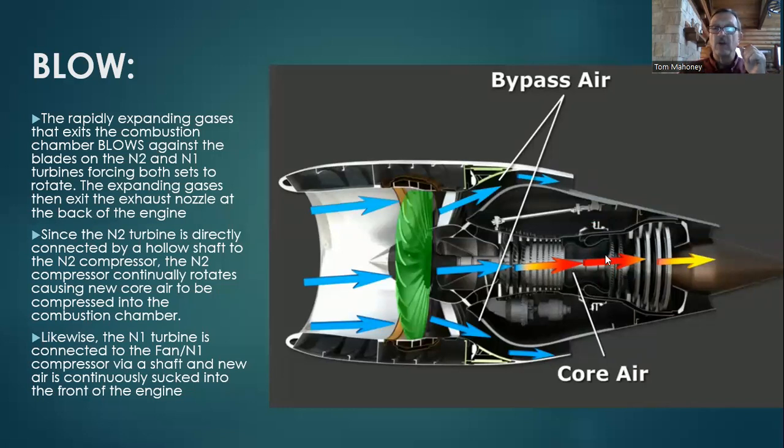As long as there's fuel being added to the burner can and the air coming from the compressor will mix with that fuel. And if the fuel's already burning, it will continue to burn. At that point in time, you don't even need to have the igniters functioning.